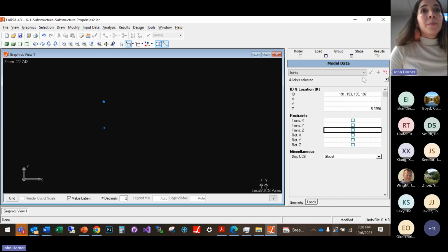So what are the restraints which are being removed? You're removing the restraints, right? Now we don't have any restraint. We will create a rigid connection member between these two, and we will have girder this way, we will have cap beam, and we will have column, and we will fix the bottom of the column. And we will have fully fixed at the bottom. So this is the restraint at the top we are removing, modifying.